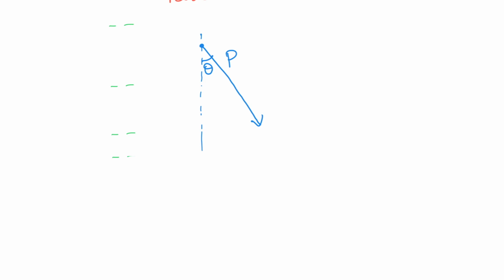You made the sense first that this arrow is going down and right, so the components should be pointing down and right. Somebody wants to make it like this. You want to go right first and then down, that's also fine. But look at my angle. Go with the angle always. If you go this way, you will have to consider this angle. So why do you want to do that when they've already given you the angle? So just go down and right. Going down and right means going straight down like this, you stop, and then you move this way, and you exactly know that this angle is 90. Now, this component is P sine theta, and this component is P cos theta.